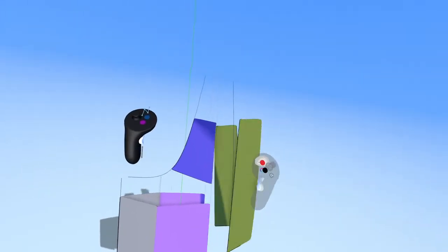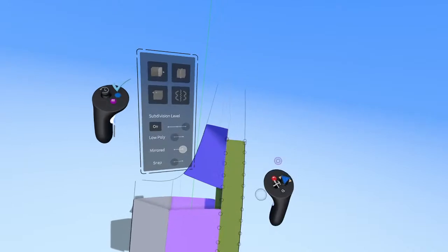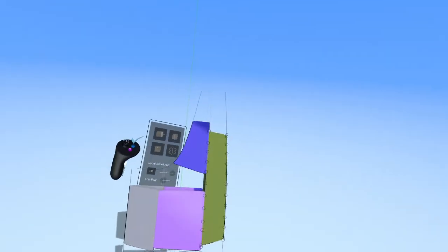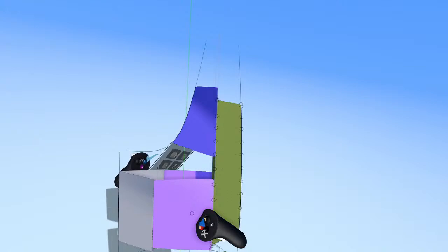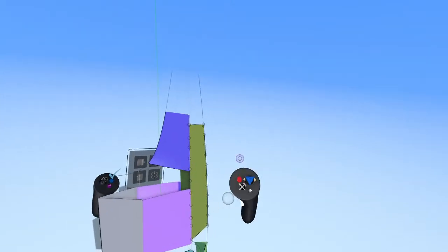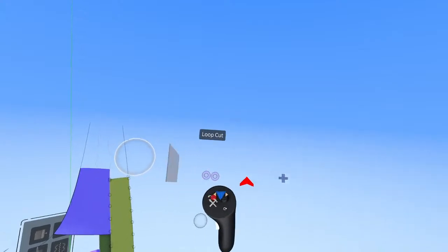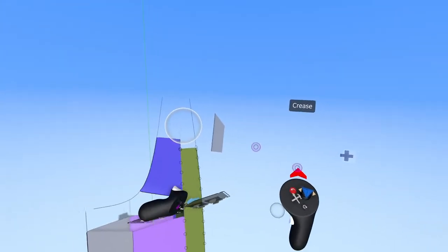To do that, you can grab a sub-D surface. Only a sub-D surface can do this. Put it into edit mode, and you'll notice that you're seeing the edit points for this surface, but not the other ones. That's because they're not merged together. To merge them together, press this hammer and brush icon, and you have these different tools that can be used only for sub-D geometry.